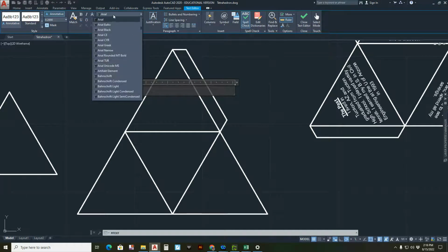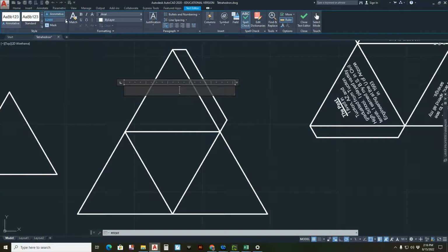There's lots of them. Your text height is this little section right here. When you start, the default is 0.20. I typed this one earlier, 0.125, but it may still be too large. You have to highlight that text and type in a measurement like 0.10, for example, before you start typing, at the bottom of your screen right here. But notice how it might reset itself back.